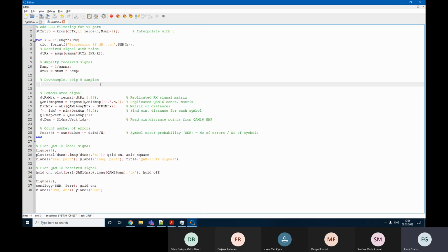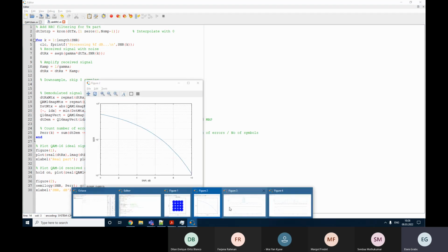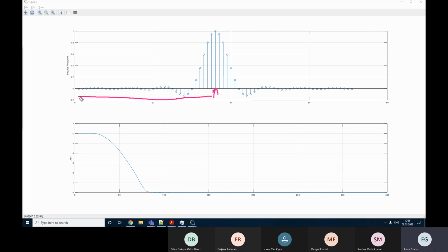But before we can do that, we need to know how to correctly read our signal, because the filtering procedure will introduce a delay. As you can see here, before our data is read, we will have some time to wait, because the filter has to calculate the output value depending on input values, and it requires the filter to fill its entire memory.